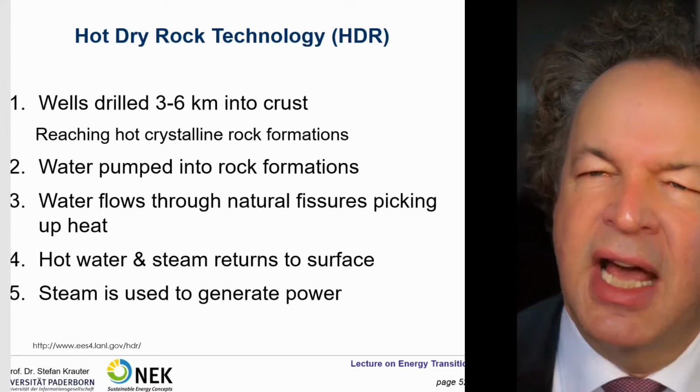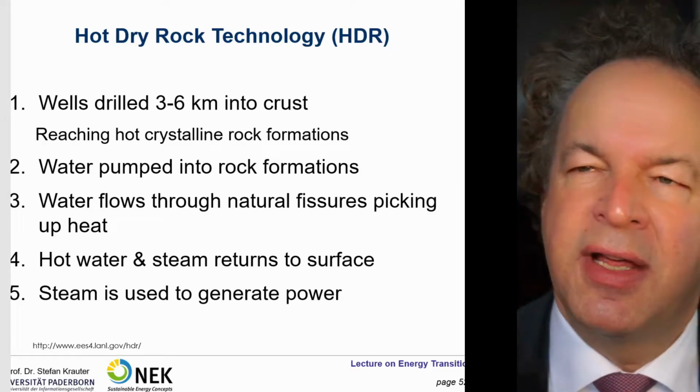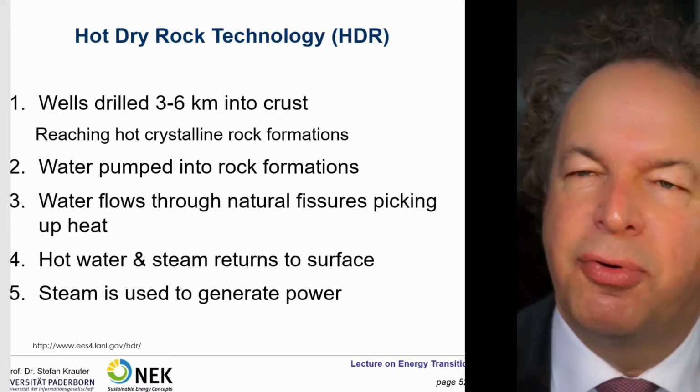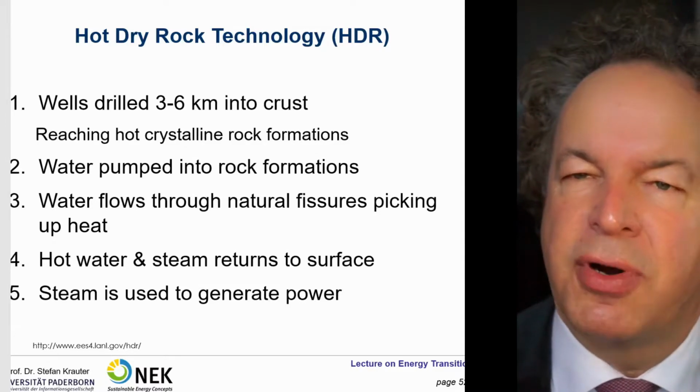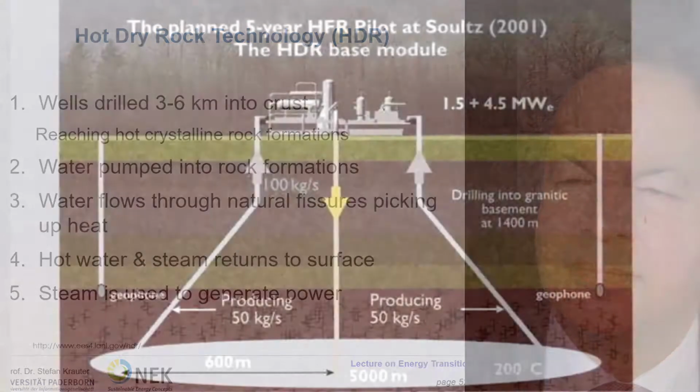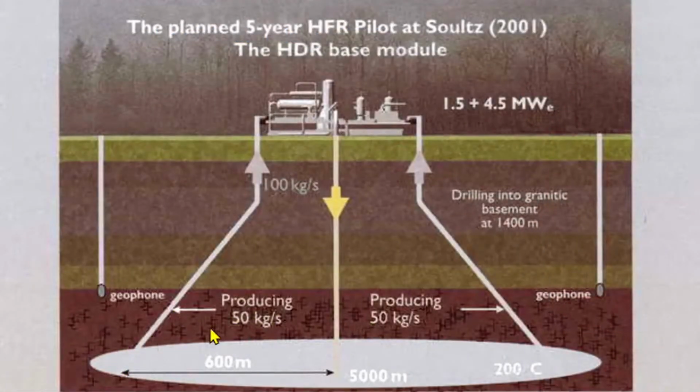By the way, it's not as in the film: it's not due to the cooling that more steam is generated, it's due to the reduction of pressure. And the reduction of pressure lowers the boiling point, and therefore more steam is created. Here we have the hot fractured rock. You have to have fractured rock in order to have sufficient hydraulic conductivity.